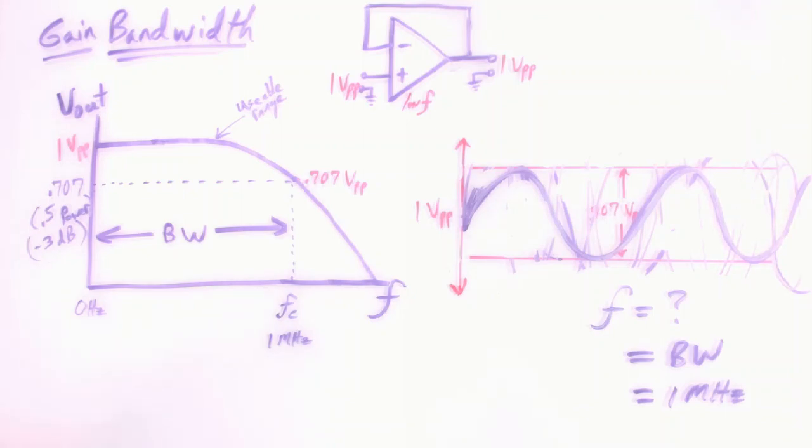They're trade-offs of each other. In other words, as you want to make a circuit with your op amp, if you want more gain, you're going to have to give up some bandwidth. It can't give you everything you want always. If an op amp has a high gain bandwidth rating, it means maybe you can have high gain and high bandwidth, but it's still going to have a limit to what you can have in both camps. So there is always going to be a trade-off.